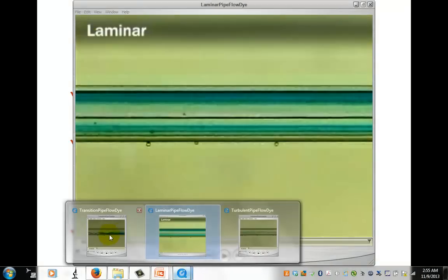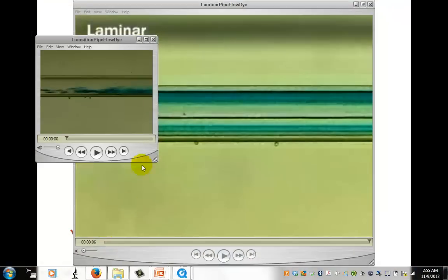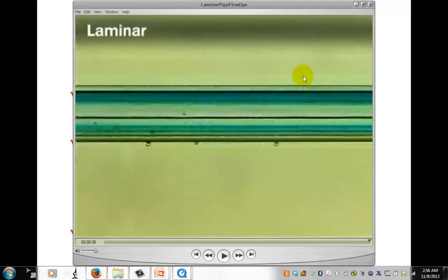In comparison to that, in a transitional flow, right around a Reynolds number of 2300, we see that sometimes the flow is now unsteady. There are vortical regions in the flow that travel in sort of chunks. So sometimes the flow is straight like this and laminar, and then sometimes there's a lot of mixing, and so the characteristic shape of the streamline shows the effects of mixing and vorticity. So here's a chunk of turbulence moving downstream. So the turbulence is intermittent in the transitional flow.